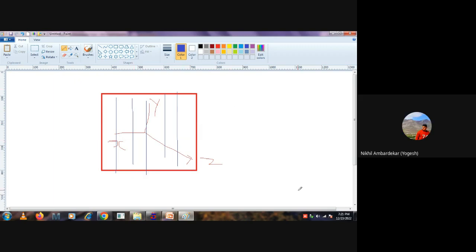So basically you have to check your local axis every time, and based on that you have to decide. It's not hard and fast that for vertical reinforcement always MY will be there or always MX will be there.